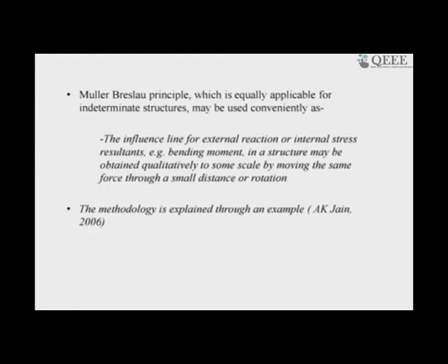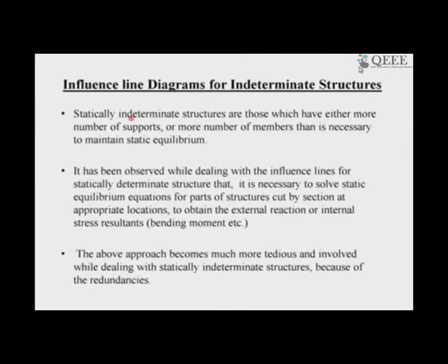So, just understand that your basic approach was to solve a static equilibrium problem for the structure, cut into separate rigid bodies, and find out either the reactions or the bending moments or the shear force as a unit load moves from one side to the other for each location, either by tabulating the values or forming the equations. That is our approach. If you apply this approach to statically indeterminate structures, there is the solution for the member forces or the stress resultants.